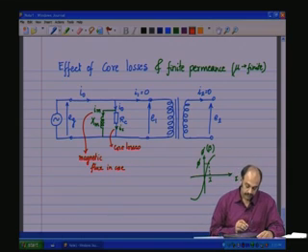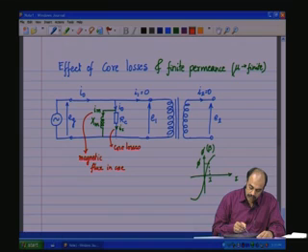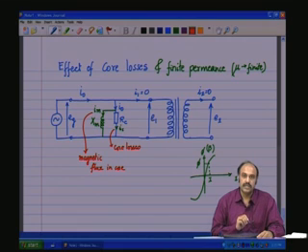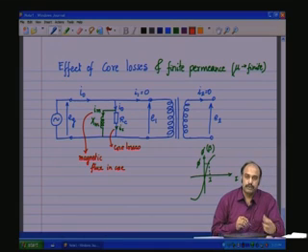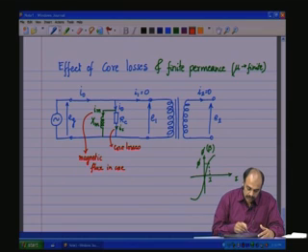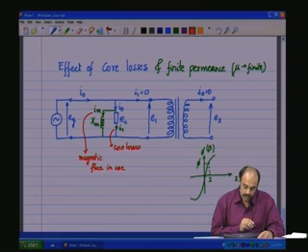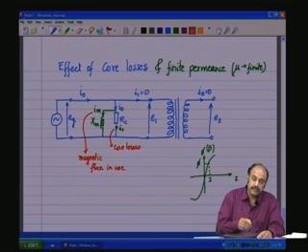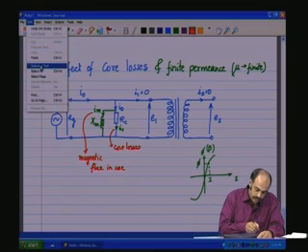How do we measure this? So, you see that IC is producing a loss in RC, IC square RC. So, the voltage across RC and E1 will be in phase, which means IC will be in phase with E1. E1 is same as EG. IM is the flux producing component which is passing through an inductive reactance, and therefore, it will lag 90 degrees whatever the voltage across the device. So, if we look at the phasor diagram, it should look like this.